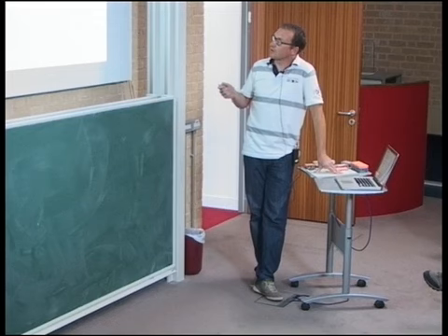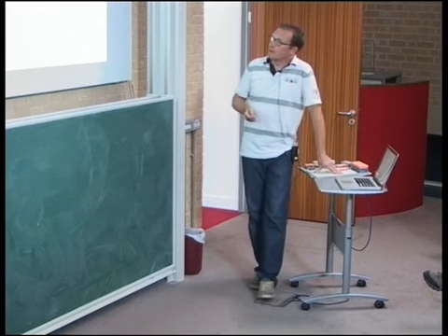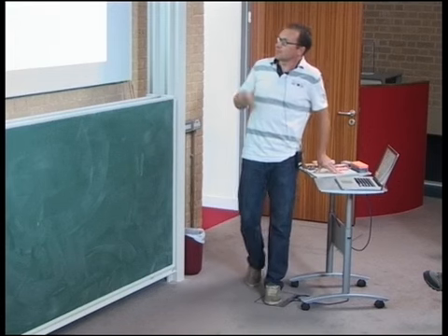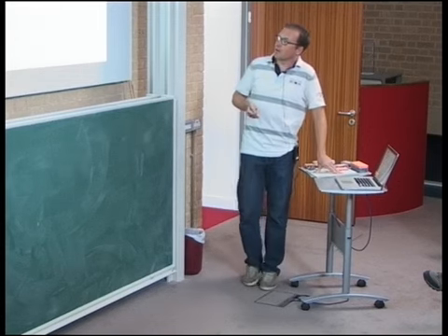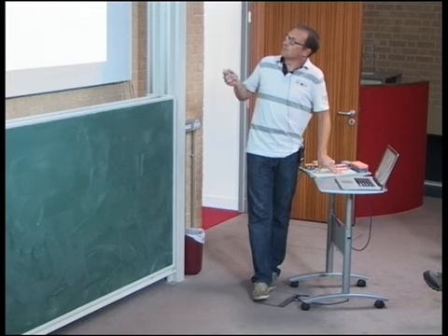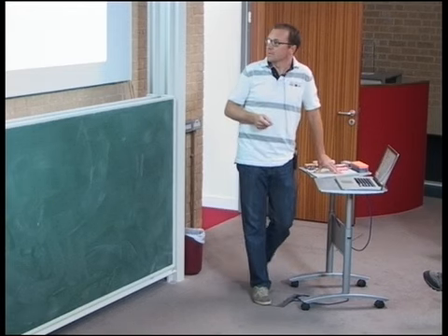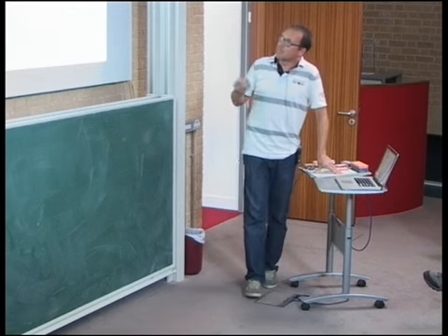So that's the bending component and the surface tension component. And then I had this conservation of volume in the cell. That's no longer needed here due to the fact that I have an incompressible flow in the cell. Okay. So this is my simple model.